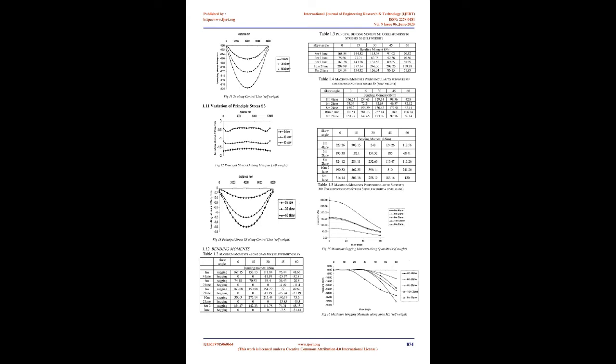The meshing was kept the same: 8 layers of elements across the depth, 10 elements along the width and 16 elements along the span. 3. For 4-lane bridges the width was taken equal to the full formation width of 19 m including 0.750 m wide curbs provided on both sides. The depth of the curbs is taken as 0.3 m. Only a single span of 8 m was considered with 5 different skew angles of 0 degrees, 15 degrees, 30 degrees, 45 degrees, and 60 degrees.